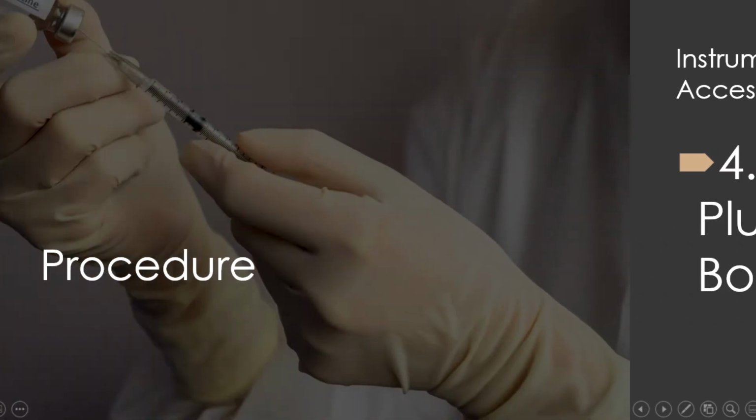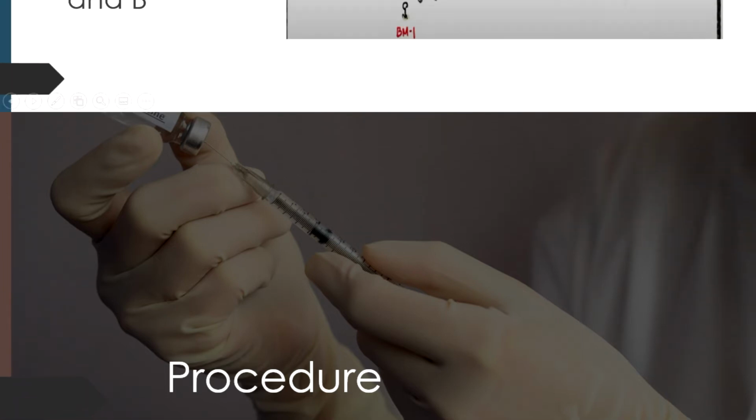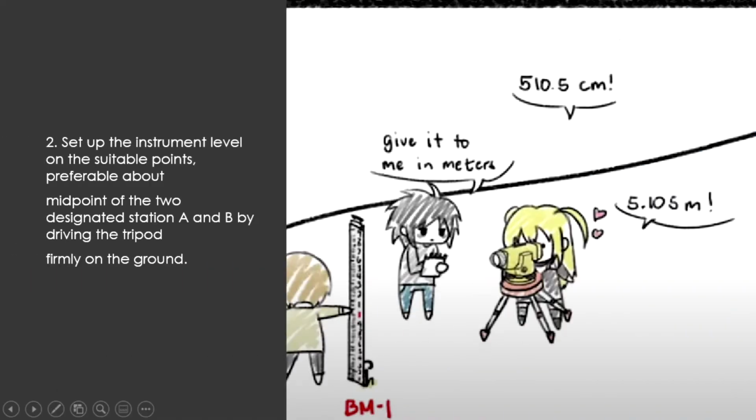Here are the procedures for the single setup differential leveling. Number 1. The instructor assigns the location of 2 points marked as A and B, which are intervisible with the instrument setup placed between the points. Number 2. Set up the instrument level on a suitable point, preferably about the midpoint of the two designated stations A and B, by driving the tripod firmly on the ground. Adjust the height of the instrument to the convenient level of the instrument man through tripod leg locks.